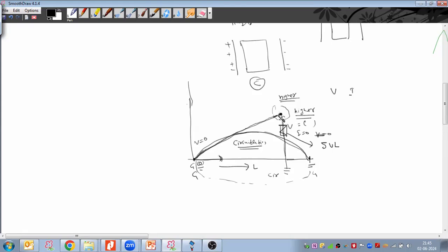If the voltage induced is under the prescribed limit, then this SVL, which is a non-linear resistance, will behave as follows. If the voltage is the rated voltage, then the resistance would be very high. And if the voltage is above the rated voltage, then the resistance would be very low. So if the rated or desired voltage is coming on the sheath over here, then the SVL provides an open path, and this terminal would be treated as an open, floating terminal.